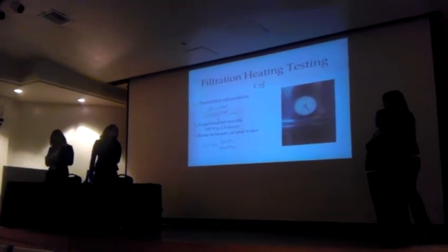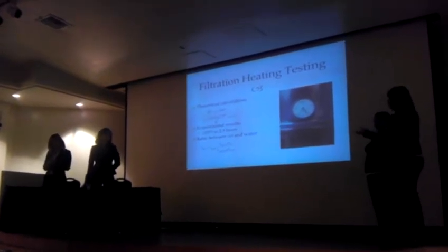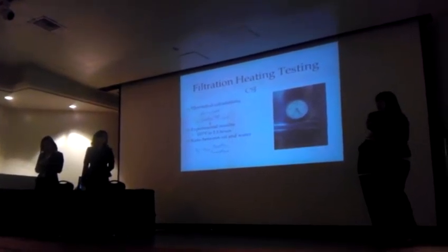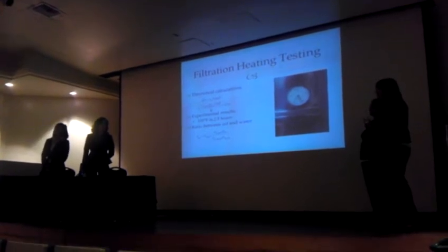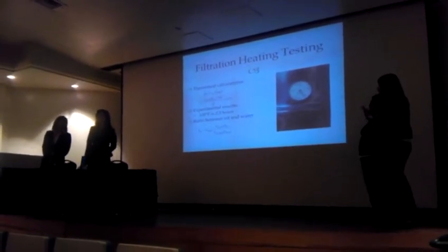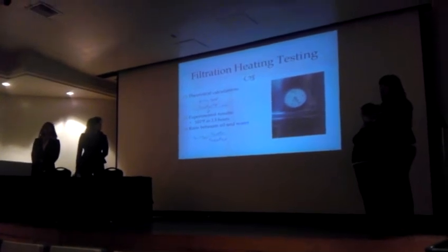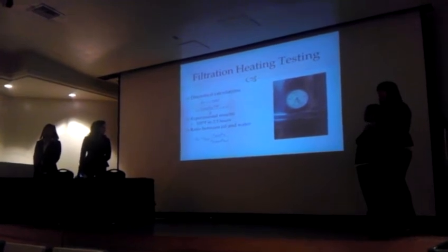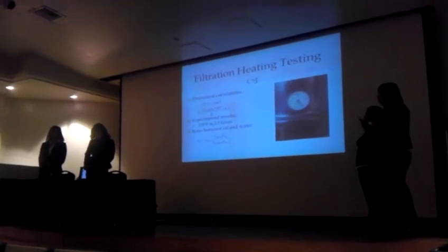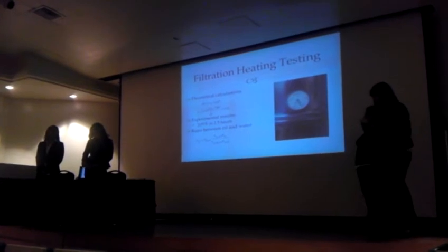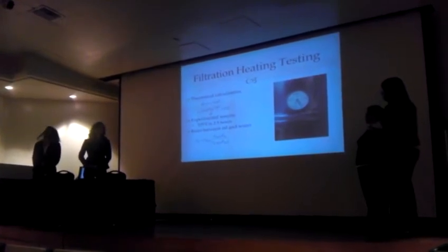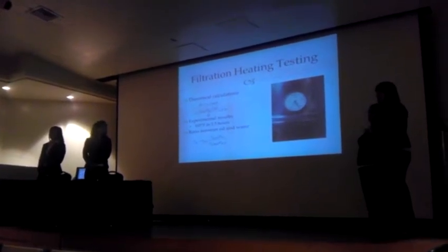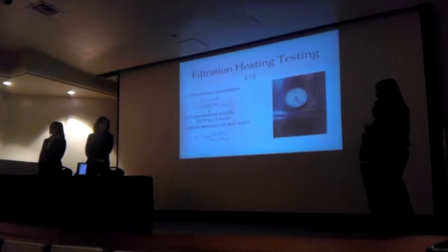So, since we couldn't do anything with oil, we ended up doing everything with water, like was mentioned. So, we had to test our filtration housing. First we had to test our heater to make sure we got accurate numbers. So, first we did all the theoretical calculations, and we assumed that our Q dot was constant, and from there we found the time it would take for the water to heat up to 105 degrees Fahrenheit. And then we did our experimental tests and found that it would take 2.5 hours, which was about the same as our theoretical calculations.